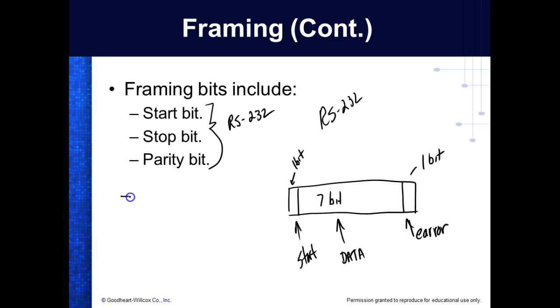So what was happening is if we weren't sending any data, the output would stay at a solid logic level. And then your receiver would be coming over here. And then what they would do is they would shift it down for one time. And this was what we call the start bit.